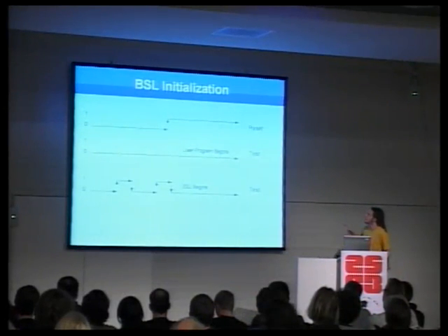If you send 2 pulses, and sometimes this is backward on another pin, if you send 2 pulses and the second pulse falls just after the reset line goes high, then instead of pushing the reset vector into the program counter, it pushes a vector found within permanent masked ROM.